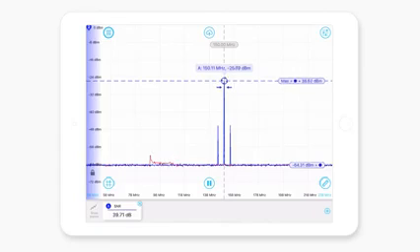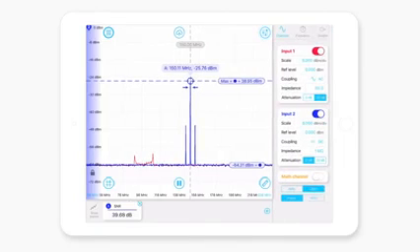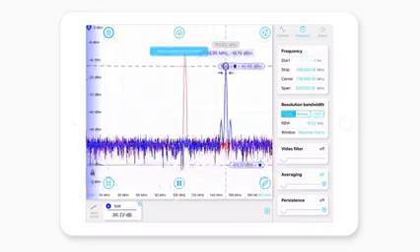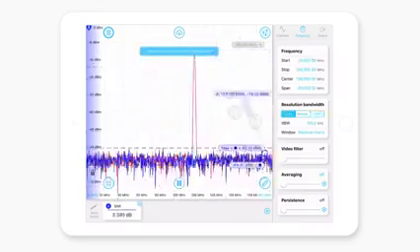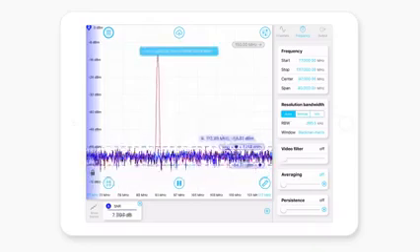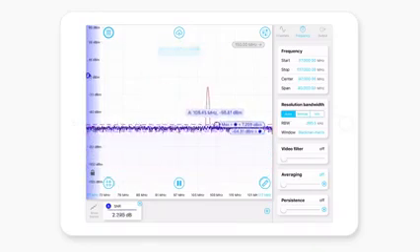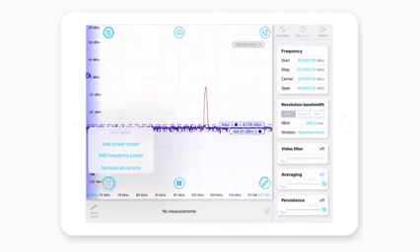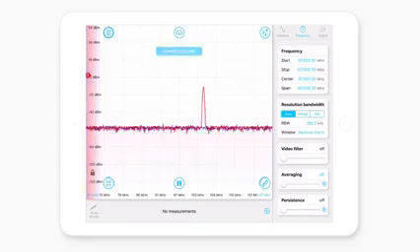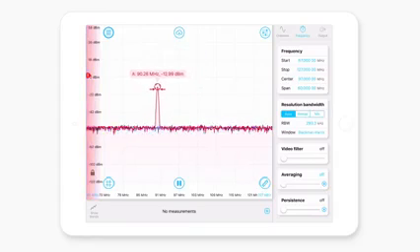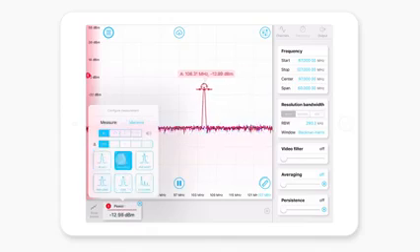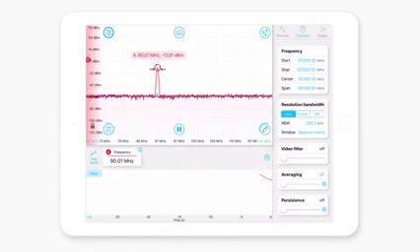The last thing that's somewhat worth looking at is, if I turn averaging off, turn that back to manual, we'll zoom right in on this guy that's moving around here. And what I'll do is remove that, get rid of all my cursors. And what I want to do is drag a marker up onto this and trace it. So I'm going to add the measurement for that marker A. I'm going to track its frequency, and then I want to show a trend of it.